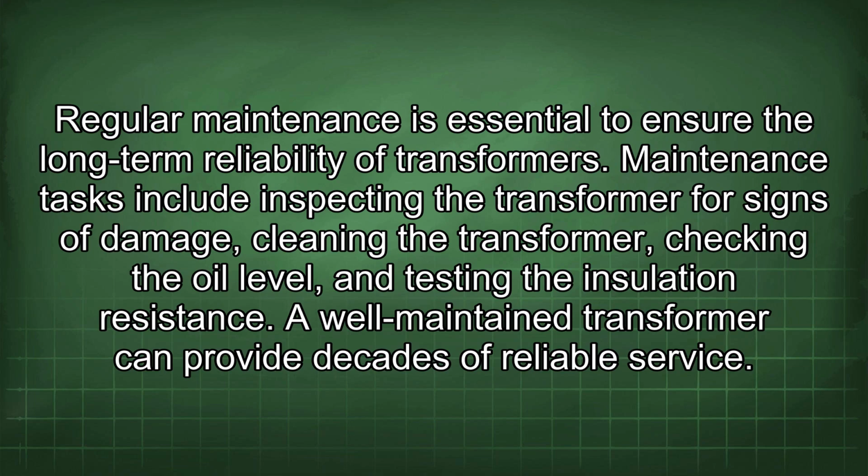Maintenance tasks include inspecting the transformer for signs of damage, cleaning the transformer, checking the oil level, and testing the insulation resistance. A well-maintained transformer can provide decades of reliable service.